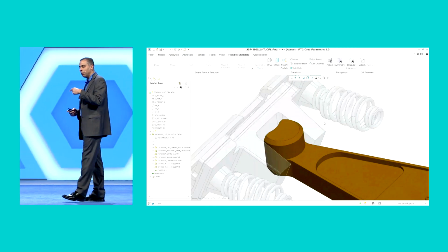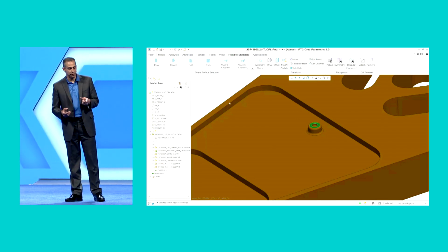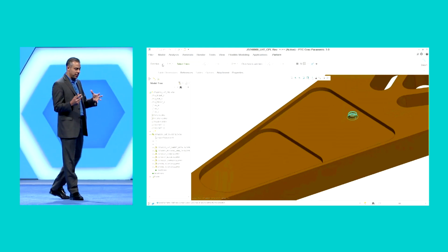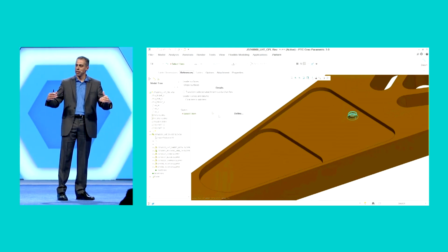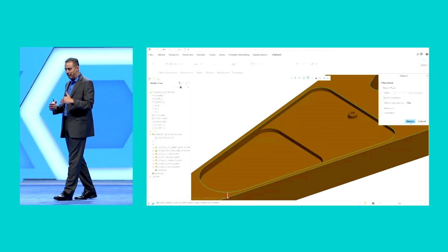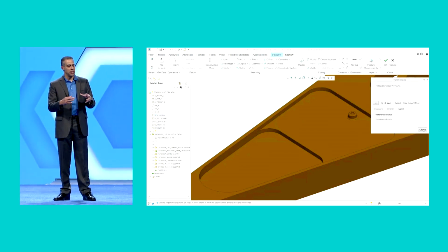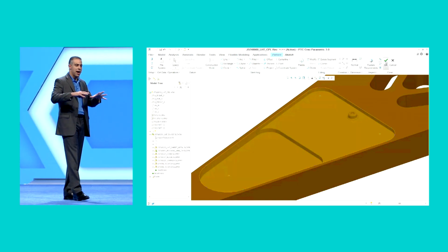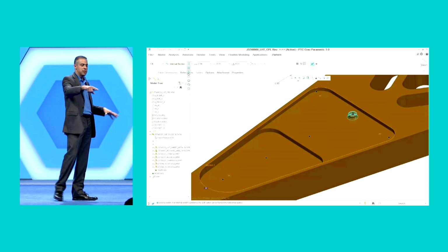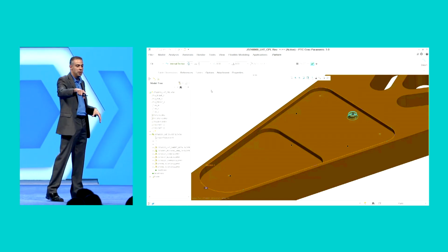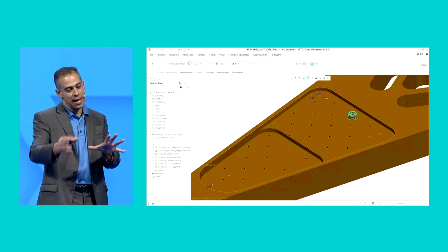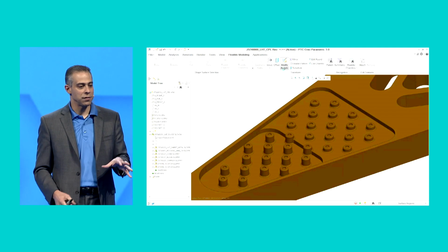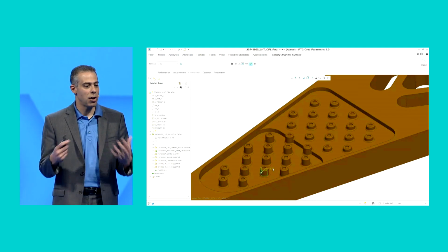We've also introduced a completely new pattern option in flex modeling. It's called a flex pattern. It's a geometry-based pattern, but the strength of this pattern is that it's got flexible modeling technology underneath it. This flexible modeling technology gives the pattern members the capability of adjusting to different topologies as the pattern members go across the surface of the part. So what you see here is we do this fill pattern of this boss. What you'll see is the boss, as it goes across that lip, the rounds, the geometry will all extend down and regenerate just fine. Okay? This is a new flexible technology-based pattern.